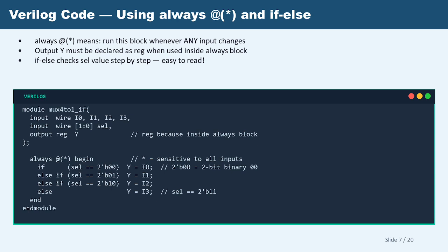So here you now have a 2 bit code, with both select lines. What is this double zero mentioning? This double zero is mentioning that both select lines are in off state. So when both the select lines are in off state, what will be the Y value? Y is going to get I0. Like that only, if else.